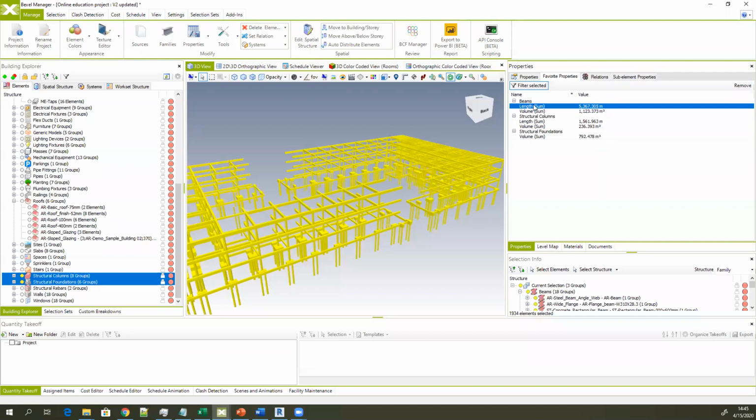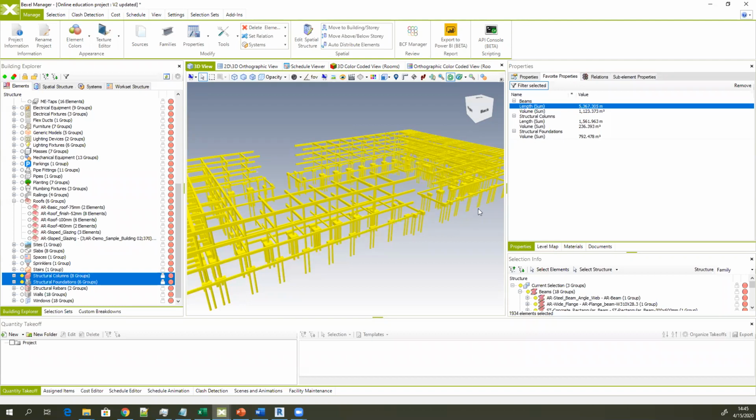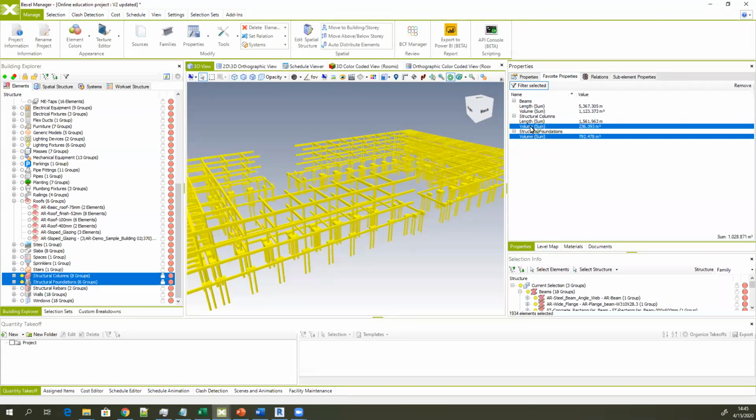And also, because these are different types of elements, if you want to see the fully summarized value for the volume of all these elements together, one way you can do it in the instant inspections, without even using the quantity takeoff module, which we're going to talk about in the next sessions, is to select the volumes and automatically the system will show you the summarized value in the right corner. So this is the total sum for the volumes of all these selected elements.